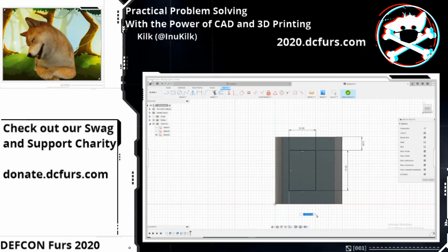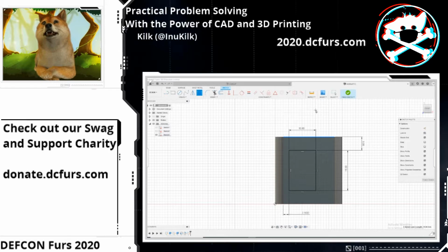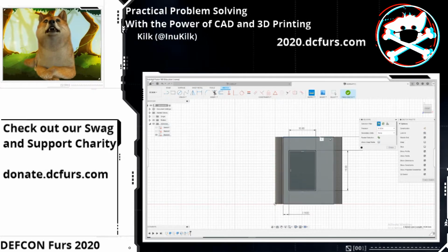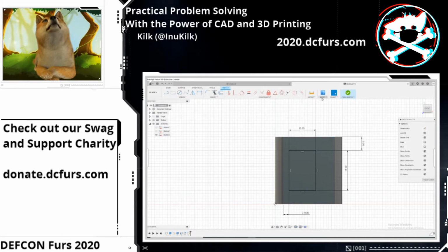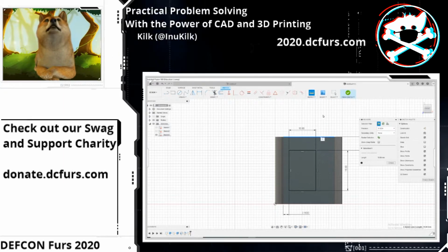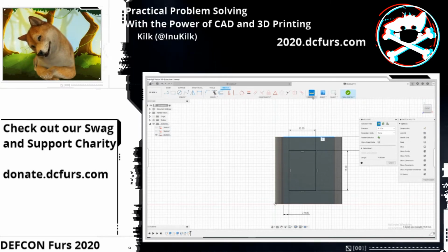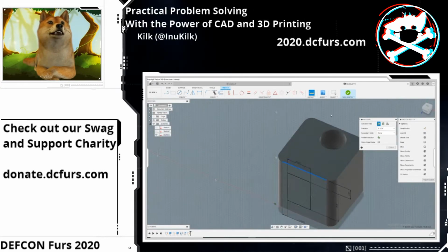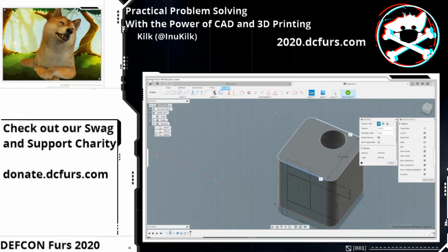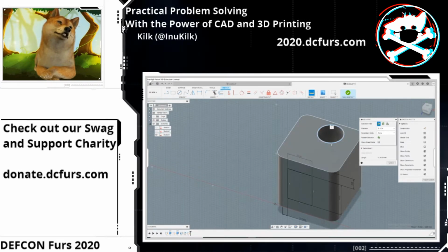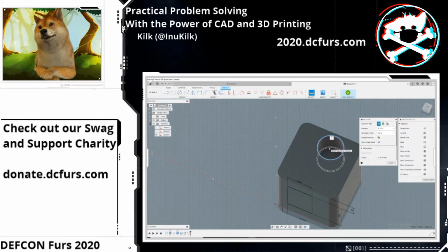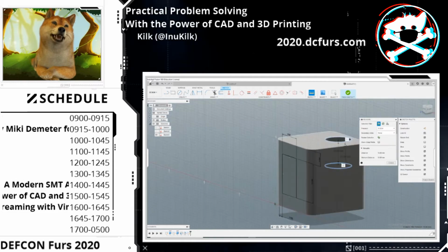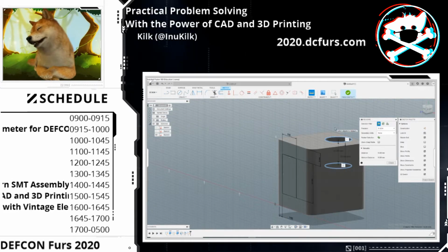And from this wall, we'll make it, oh, wait, there could be something that might be useful. Let's first find the dimensions of the, never mind, don't do that. Use the inspect. Oh, wait, that didn't measure. There we go. So, here's a tool I just used. If you click here and you hit measure, which is I, so if you hit I because you're inspecting it and you select an edge, it's going to, well, if it works properly, can you work, please? If you click this, it'll tell you the length. And now if you select 2 edges, it'll tell you how far they are. This is useful because if you do something like, I want to know how deep this hole is because I forgot how deep it was. If you click the top ring and then the bottom ring, it'll tell you exactly how far away it is, so you know it's 10 millimeters deep.